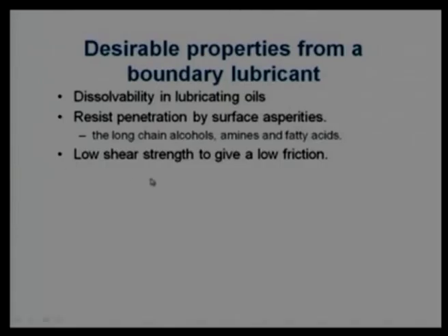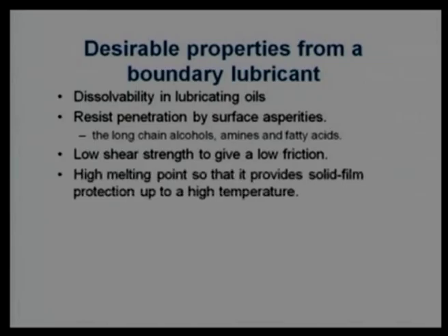If these boundary additives are not able to give us a low shear strength of the interface, then they do not have much use. So you need to have low shear strength, either by directly attaching to the surface or by chemically attaching to the surface. In addition, we can demand a high melting point, so they do not get disturbed as the temperature increases.